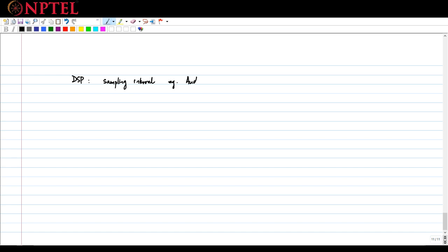For example, for audio, let's say that I'm dealing with 16 kilohertz audio, which implies that the sampling interval is 62.5 microseconds, right? So in other words, every 62.5 microseconds one new sample is coming in. But let's say that the hardware that I am building, some kind of processor for audio, takes in samples at 16 kilohertz and needs to do some processing with it.